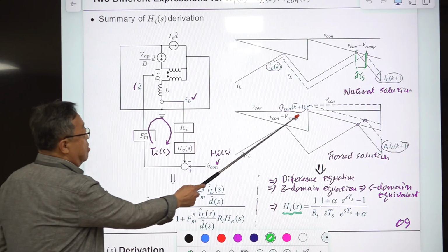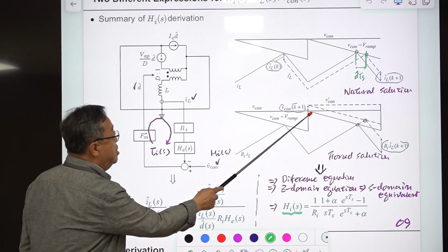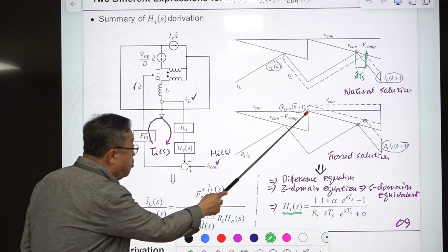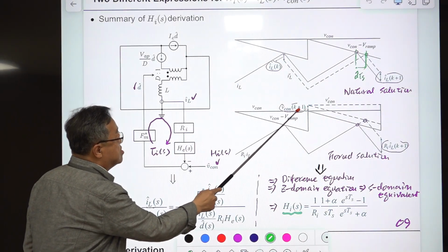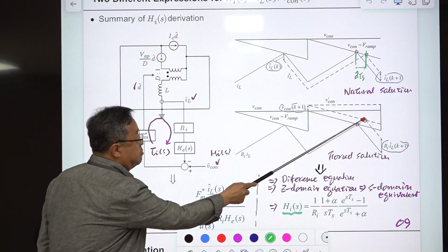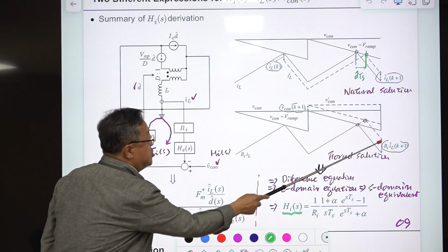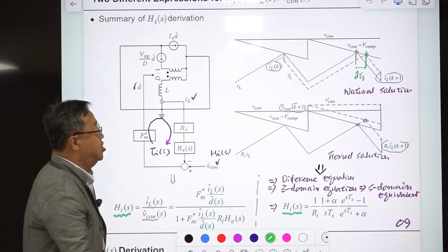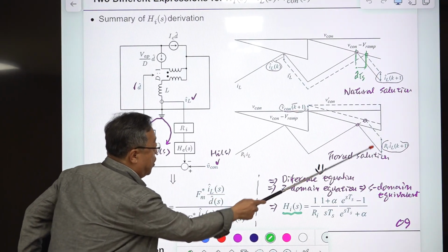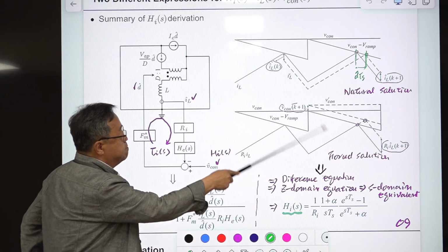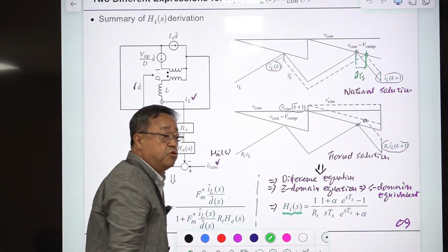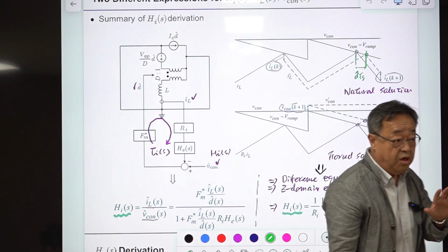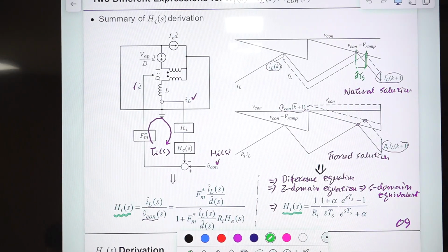Forcing function is perturbation in this control voltage. So control voltage is assumed to jump at this point, and the perturbation is changing this PWM point, and this is the result of this perturbation, propagation of this perturbation. So we derive the transfer function from here to there. The step is very similar to this. We use the geometrical construction of this. We used this time interval and the slope of various waveforms associated with this PWM function.